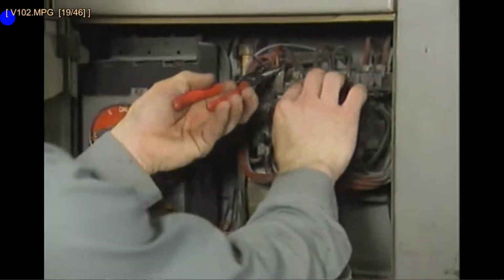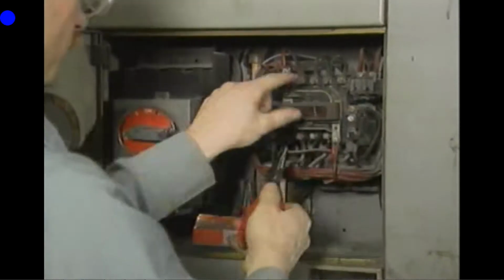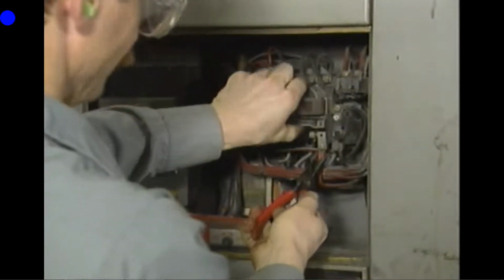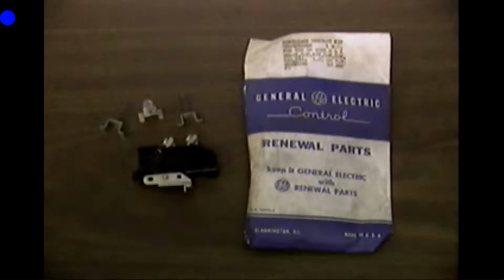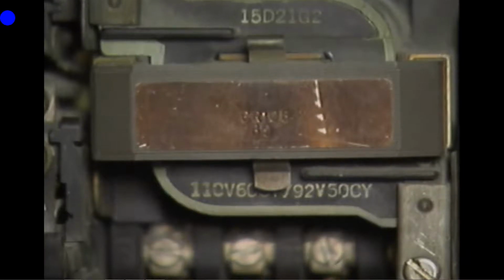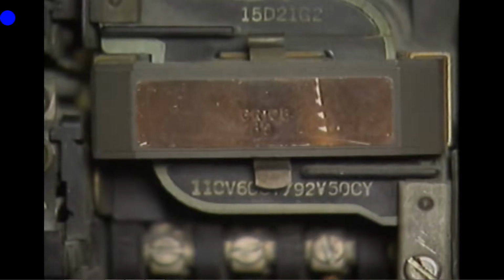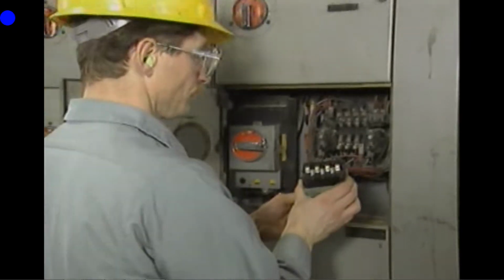Once the cause of the controller problem has been identified, the next step is to make the necessary repairs. Repairing an AC motor controller often includes replacing components that are malfunctioning. When replacements are made, the new components must be the same size and rating as the original components. If the cause of the malfunction is defective or damaged contacts, you should replace both the movable and stationary contacts at the same time so that they will make good clean contact when they're closed.